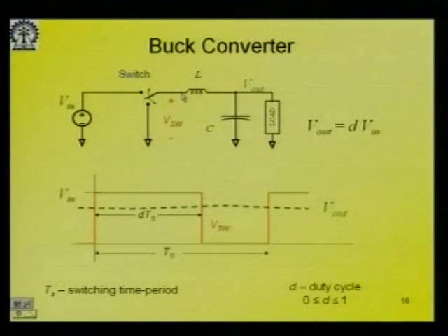So the integral of L di is the flux stored in the inductor, and voltage times dt will be equal to that value. Since an inductor does not keep accumulating flux over every cycle, when the circuit is in the steady state, the voltage times the time across the inductor balances over each cycle, that is, it will be equal to 0.